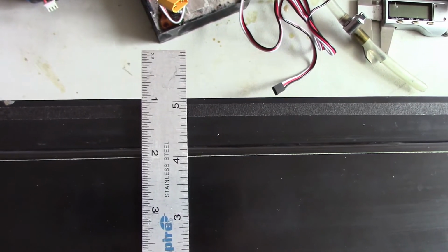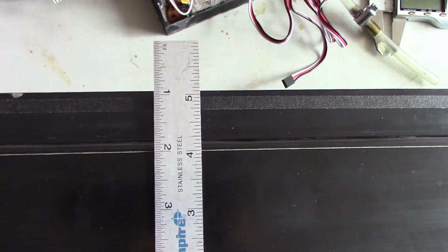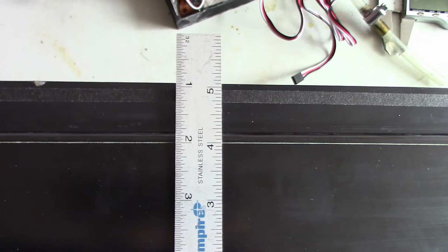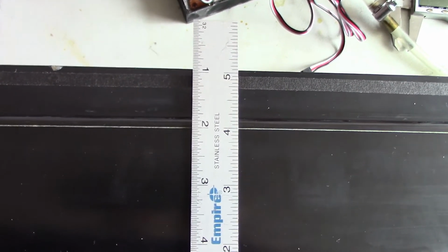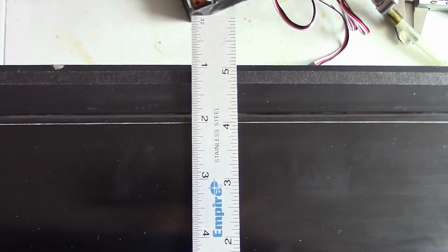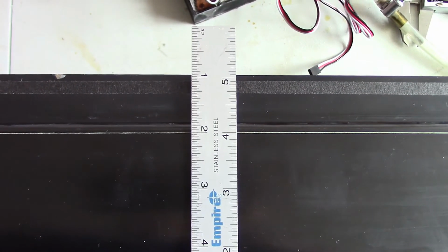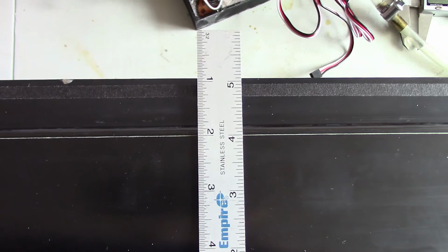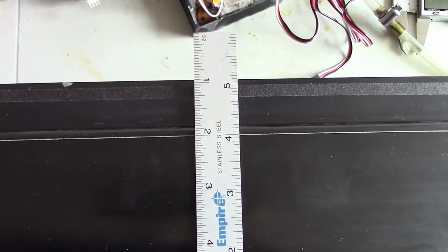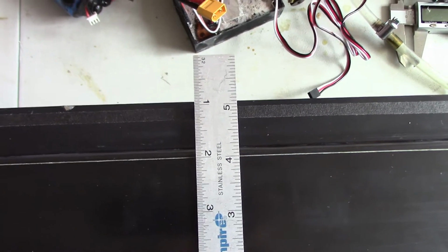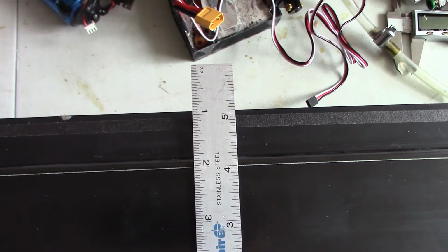Now you lighten it up, more freeboard's going to show, but then the bottom of the windows is actually going to move up too. So if you mark the water line with kind of no buffer, then you're setting yourself up for the chance that if you guessed your weight wrong, you're going to have to cut out the windows again in the future when you decide that you want the boat to be lighter.